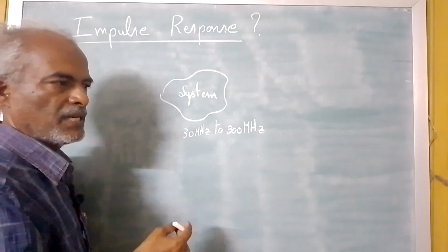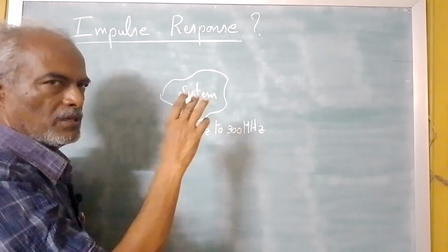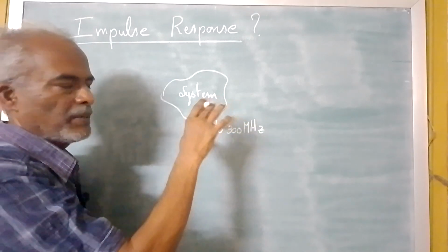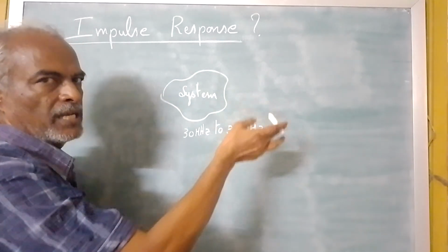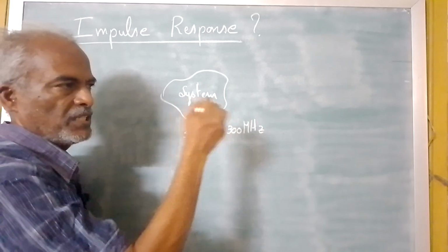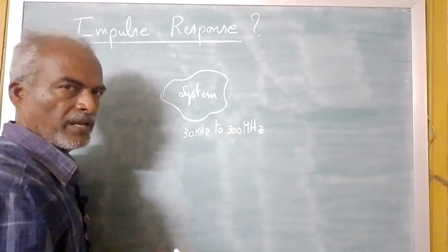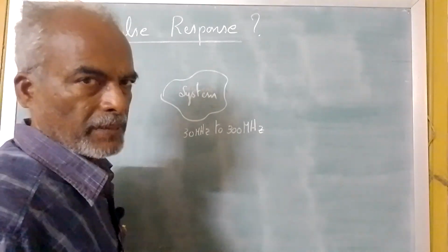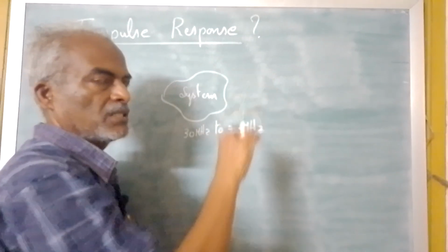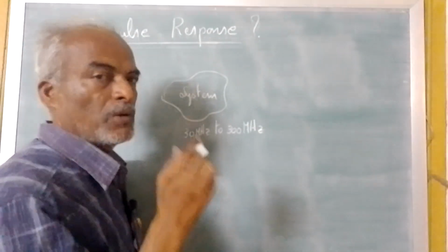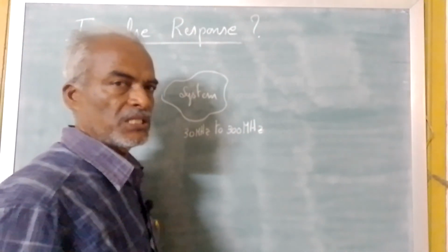Generally, we go for the frequency response by connecting a source and an oscilloscope at both ends, and we test each and every frequency. That is one way. The second way, practically, is to use a spectrum analyzer to check what frequencies the system is allowing. But what is the input that we have to give into the system?